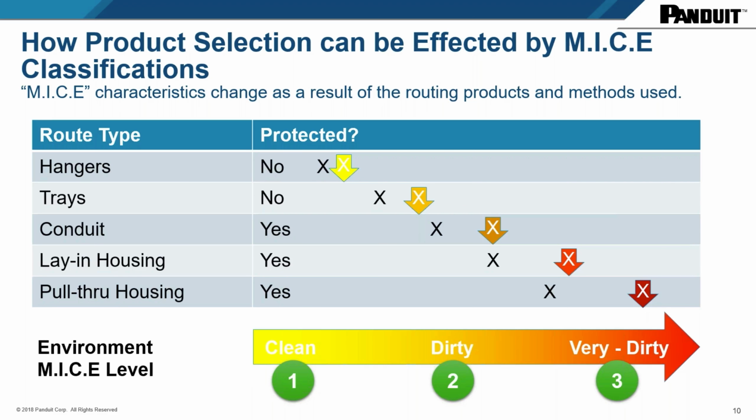So how do we protect our cables? If you put your cable inside of a conduit system, then you're basically changing what you call a commercial grade type cable. If you put it inside of a conduit, you give it an additional protection so it can take a more dirty environment because the conduit is protecting it. You have to worry about condensation, and that could be an issue.